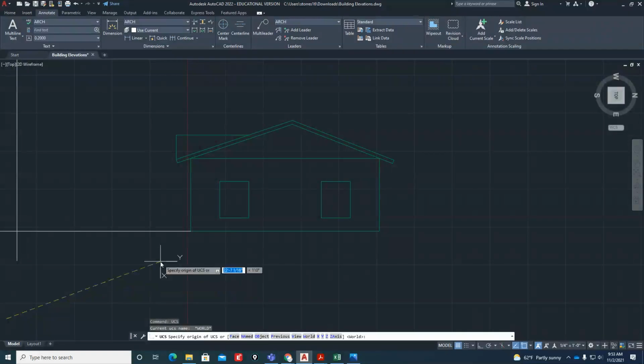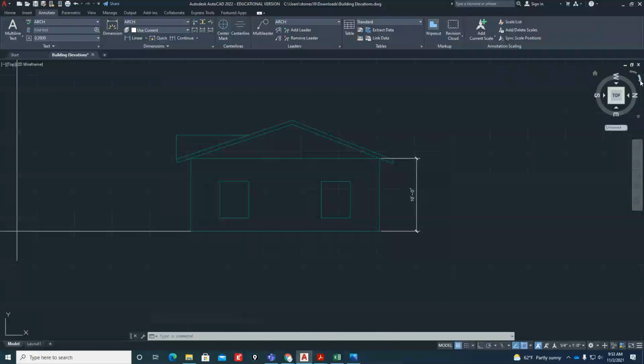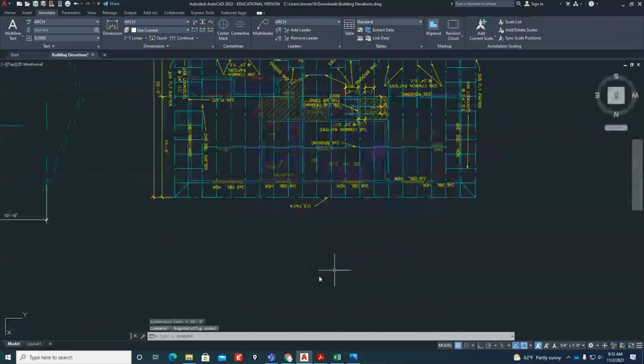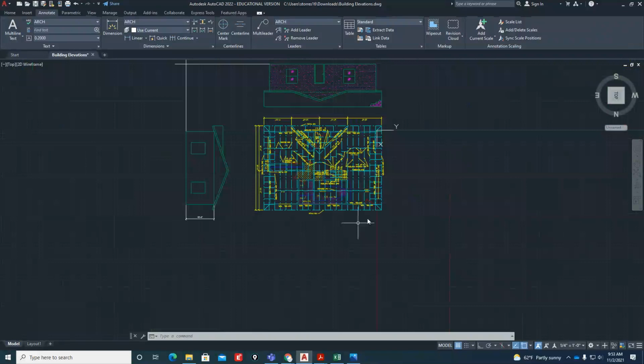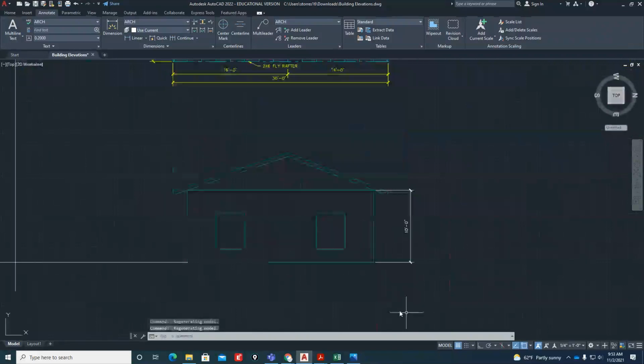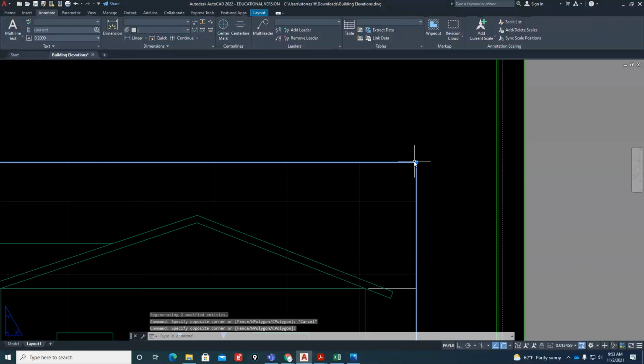So what I'm going to do is simply flip the X and Y orientation of the UCS, and then just change it to this current view. That way, the Y is now oriented up. So when you put your dimensions, everything will come out the correct way. In some cases the text will be upside down, especially on the backside view. If you don't orient your UCS correctly, all your text will be upside down. So just be aware that you do have to adjust your UCS in some cases. That way, when you label it and put it on the viewport, everything will be oriented correctly.